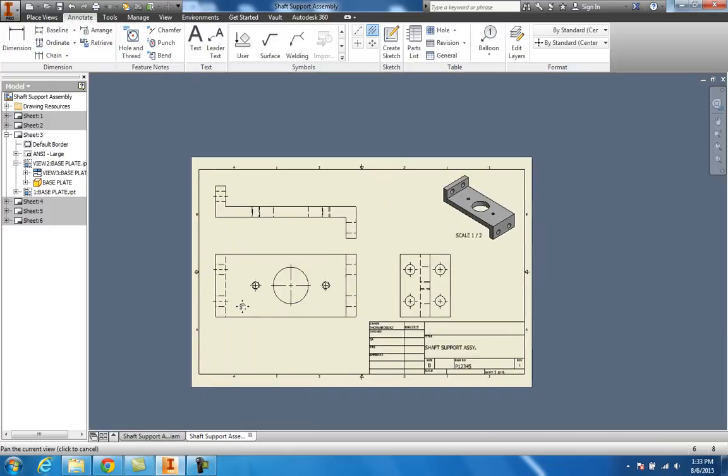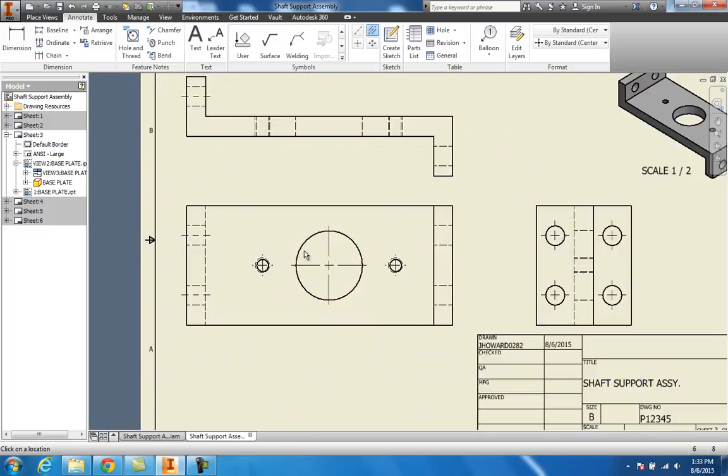And don't forget, whenever you're dimensioning something that's round like this, circles, always dimension them like that. Don't come up here and dimension, and don't try to dimension, well, I don't have a center line in there, but don't try to dimension it like this.